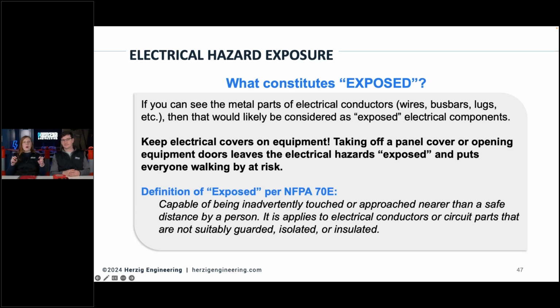So the exposed part is capable of being touched or approached nearer than a safe distance. That is more specific to the shock hazard. Whenever we're talking about arc flash hazard, even if you can't touch it, like you reach your fingers in that little knockout and you can't touch anything, great, fine. But you could still have that energy blowout from an arc flash. Another example would be those touch safe plastic guards. You put your hand on it, you're probably not going to touch anything. Don't be doing that willy-nilly just to test it. But you're not supposed to be able to touch anything and get shocked. But there is still enough of an opening that something could fall in and cross phases and cause that arc flash. A little piece of plastic ain't gonna stop that.